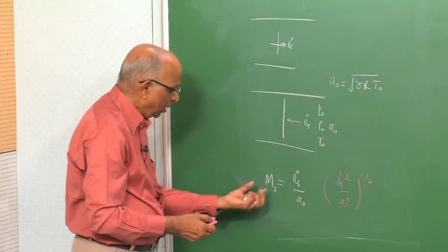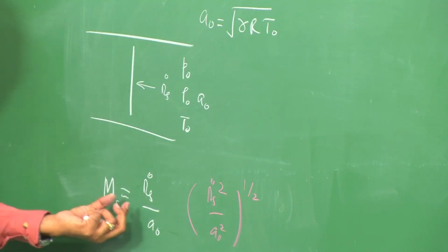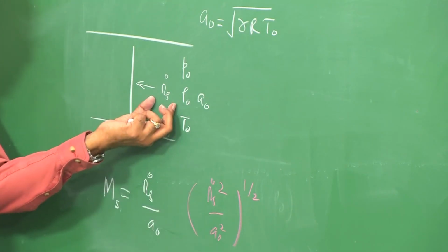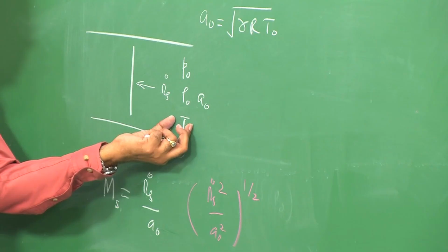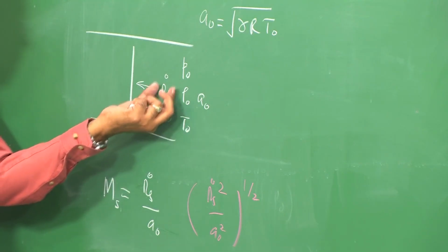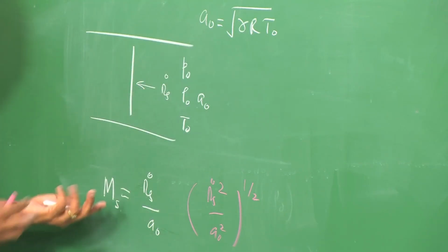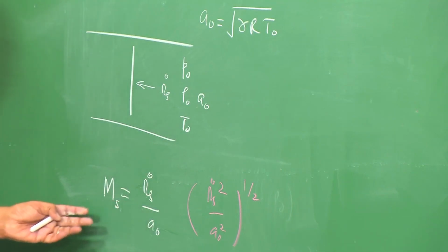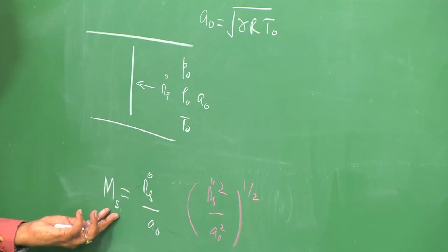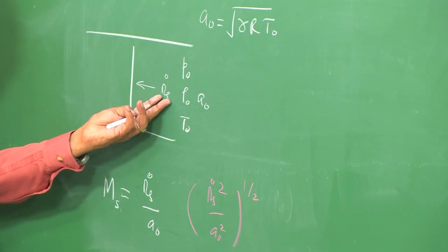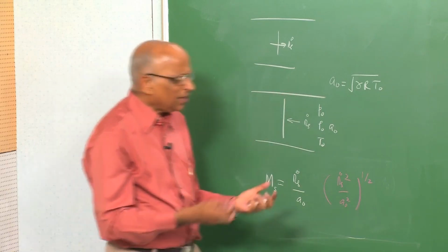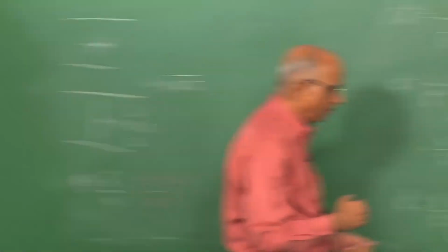Therefore, Mach number is a representation of the kinetic energy of the gases to the molecular or internal energy of the gases, and as the internal energy increases for a given velocity, the shock Mach number comes down. It is just the ratio of the kinetic energy to the internal energy, and therefore, we will use the Mach number instead of the shock velocity to be able to derive an explicit expression. Let us do that. Let us get started.